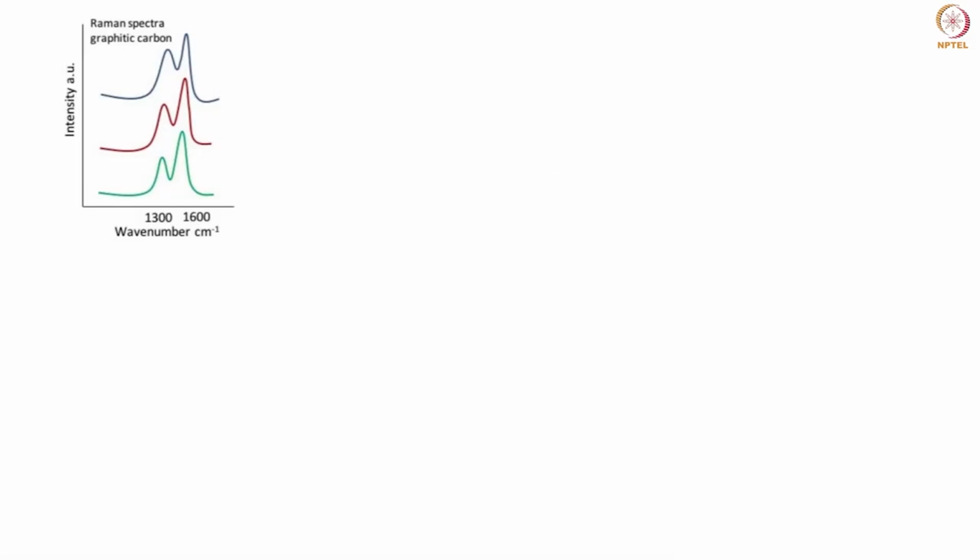Okay, so I have again pasted all the Raman spectra here. So this is some carbon material. Let's say it is some sort of disordered carbon material. We get it from polymer and we keep on heating it, say at 900 degrees centigrade and then at 1000 degrees centigrade. And let's say this one is at 1100. So we need to find out what is the optimum temperature, or if there is any increase in the graphitization or the graphitic content in our carbon material. So can we do that using Raman spectrum?